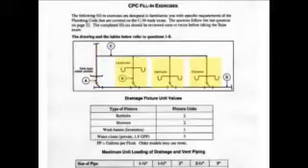So we need to add up the fixture units for the lavatories, the bathtubs, and the showers. Let's see what they are by the chart. Start with the lavatories. We have 2 lavatories, 1 fixture unit for each lavatory, so that makes 1 plus 1, 2 for the lavatory area. For the bathtub area, the bathtubs have fixture unit values of 2 each, so we would have 4 total at the bathtubs.